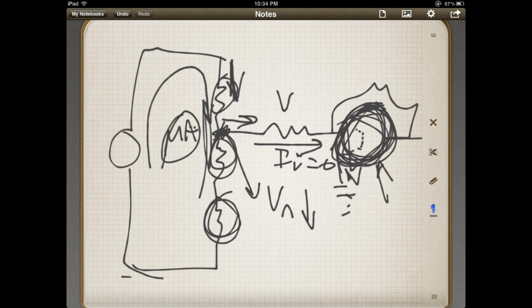And it depends. Like I said, if you're working in amps and you've got an op amp whose leakage is nanoamps, well then it might as well be an ideal op amp, because the difference is so huge that it doesn't matter. The op amp is never going to see that. So that's what you have to keep in perspective. Keep your mind in that realm of what am I working in? And if I'm working in microamps and it's operating in microamps, there could be a potential problem. So look at it, okay?